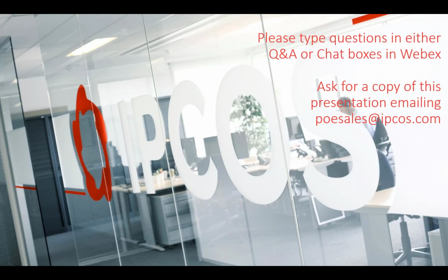Anything using soft sensors? That's another question. Yes, that basically is something we will talk about in the next webinar: how to use those soft sensors specifically for advanced process control. But in the cases when your analyzer is not reliable enough, for example, maybe your composition control can be done using some soft sensors instead of using an analyzer only. So you can use that. Sure. But again, we will go into a bit more detail about soft sensors in the next seminar.